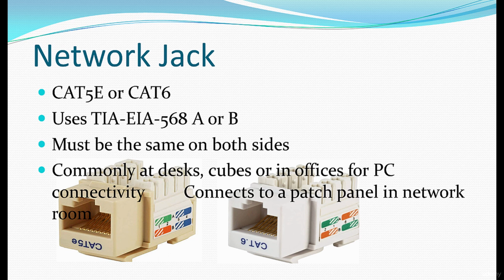These are network jacks. These are Cat 5e or Cat 6 jacks. Uses the TIA/EIA 568 A or B standard. Again, you have to use A or B on both sides. Commonly at desks, cubes, in offices, for PC connectivity. Connects to a patch panel in the network room.